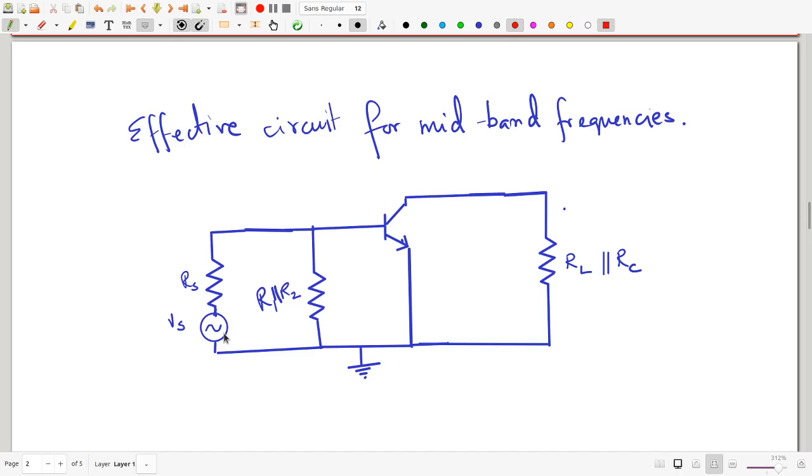So basically what you have is effectively an insulator sandwiched between two conductors. This, of course, gives rise to capacitances. These are not capacitances you want, these are stray capacitances which come in because of the way transistors are constructed.